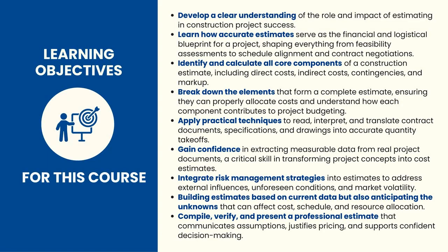We're going to integrate risk management strategies into estimates to address external influences, unforeseen conditions, and market volatility. Building estimates based on current data, but also anticipating the unknowns that can affect cost, schedule, and resource allocation. And compile, verify, and present a professional estimate that communicates assumptions, justifies pricing, and supports confident decision making.